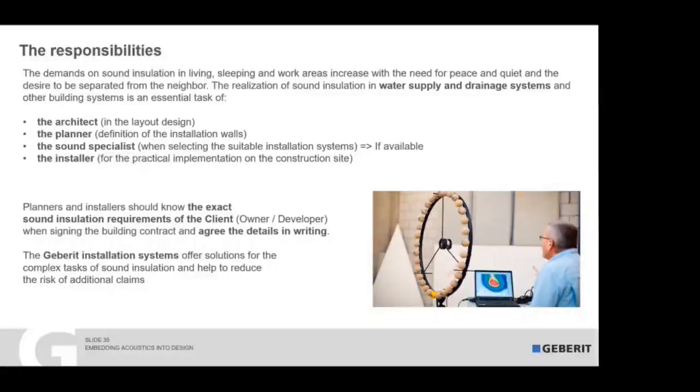acoustics in this case when you have a blockage. Yeah, if I get what Yogesh is saying, with regards to the standard, you mentioned the criteria, which is like 30 dBA, 35 dBA for living space, bedroom areas. But if a toilet is stacked within the toilet, I had it in the past as well, where contractors say, guys, this is a toilet, you will really need to specify acoustic drainage or DB20 pipe for the toilet itself. So in certain instances we end up having an amalgam, a two-pipe system. Normal drainage pipework within the toilet, just normal plastic pipes sometimes, or HDPE, whatever it is, and then acoustic pipe within sensitive areas or habitable space like bedrooms, kitchen, living space. Okay.